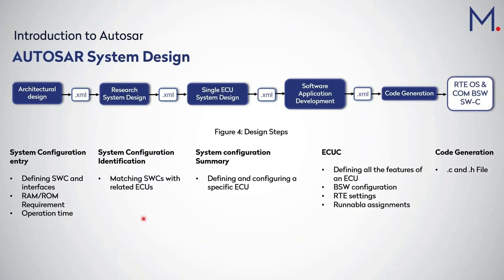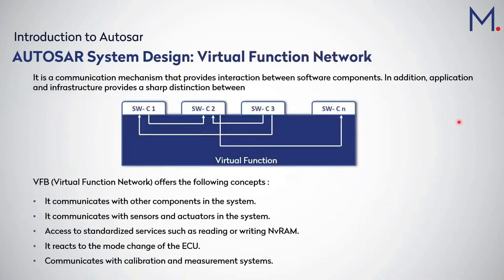If we add a new software module, then the configuration file will be updated. If you configure something, if you add a new UDS service, if you change a parameter of CAN communication, then the configuration file will be updated. And with this configuration file, using Autosar tools, you're able to generate the code and integrate it into our ECU. So this was the part of basic software.